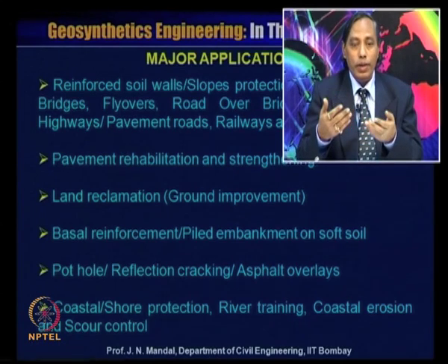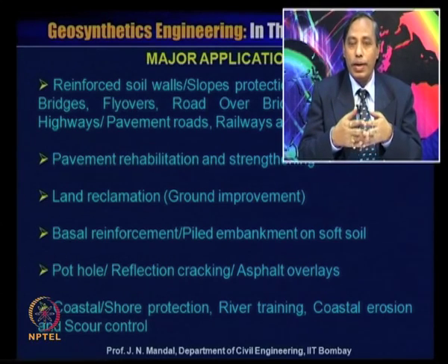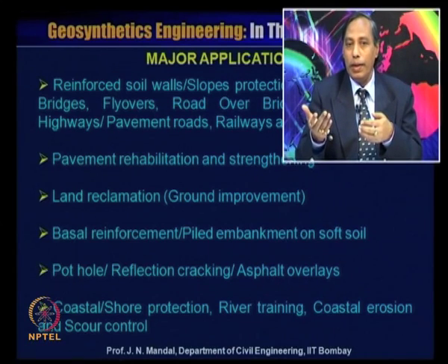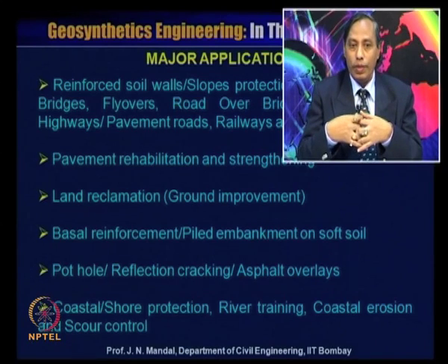It depends upon what kind of pothole it is, and what kind of cracking pattern, whether it is alligator cracking or longitudinal cracking. So, you have to be very careful about the depth and width of the cracking pattern, and then you have to select the proper kind of material to control the reflection cracking or pothole.